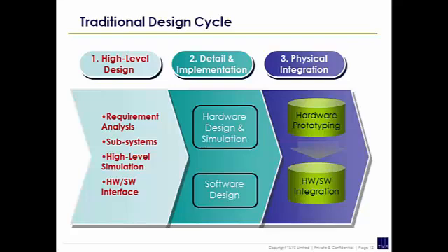The second thing is co-verification can be helpful for system stress testing. Instead of running in simulations for long hours, just go for prototyping of that or put it in an emulation and make it faster and stress the device as much as possible. So anything which is supporting emulation is kind of helpful in co-verification as well. That is the bottom line. Emulation supports co-verification and has got good EDA support. This is a plus point.